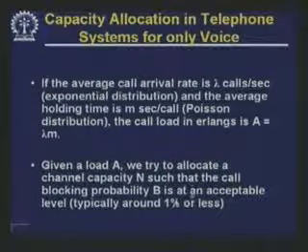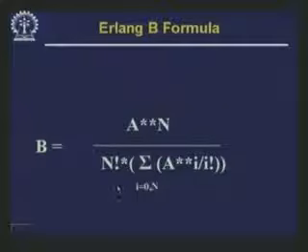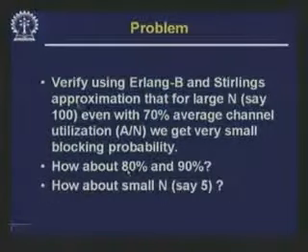This is the typical figure that we try to achieve, that even in the busy hour we get not more than 1% call blocking probability, and the formula for calculating this is: B = (A^n / n!) / (sigma of A^i / i!). Okay. So, you can use this formula, or maybe write a small program using this formula to calculate the call blocking probability given these values of A, n, i, etc. i, of course, is this thing. So, you can verify this.